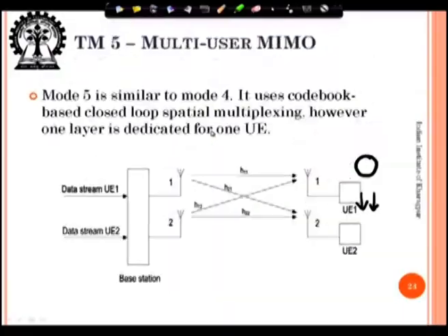So, in beamforming, amongst different modes, one can think that if one has knowledge about the channel at the transmitter, then what could one do? One could essentially do the SVD of the channel and find the different vectors of V, and if one uses the appropriate V vector, then what one is essentially doing is conditioning the channel towards the particular eigenmode. So that is very, very fundamental. So one could do that and achieve many important outcomes. So we move on,